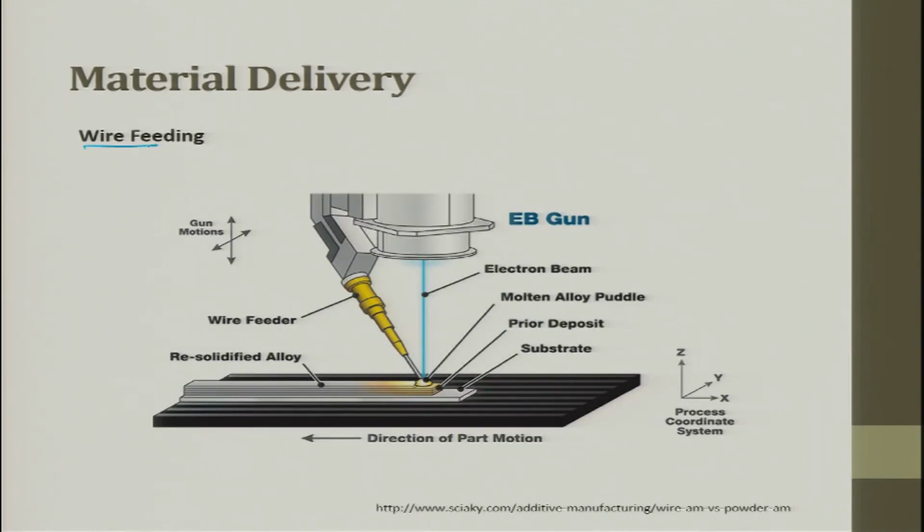So, wire feed. This is the wire which is getting fed. It looks like your MIG system and TIG system. So, this is a wire feeding coming up. Here is a laser. So, this laser or the electron beam comes and hits at the pool, and here it melts. Here is a melt pool we talk about. This is the molten, they call it a puddle, we will call it melt pool. So, this is the wire coming here, electron beam can be replaced by laser.